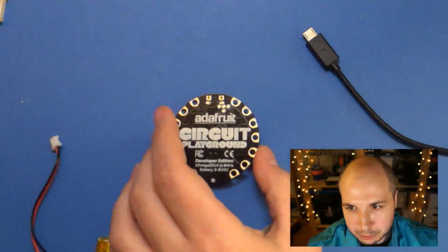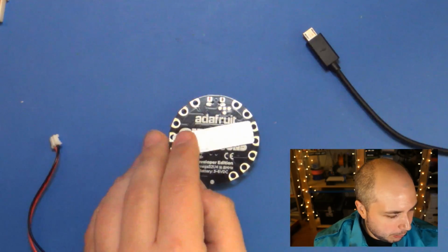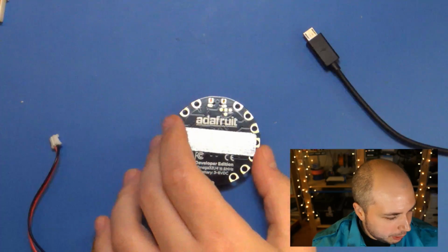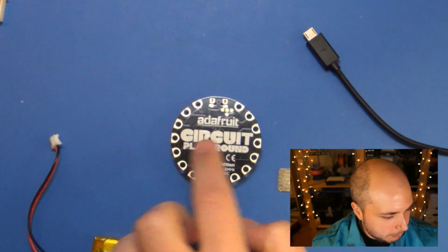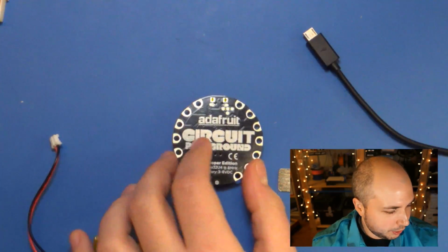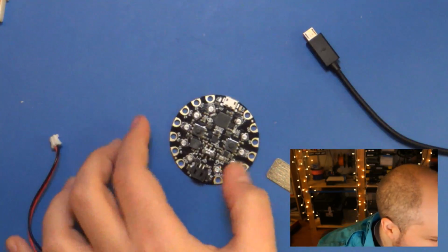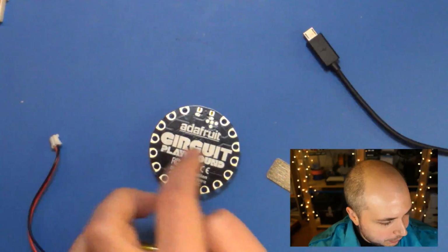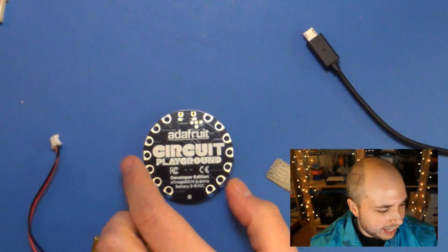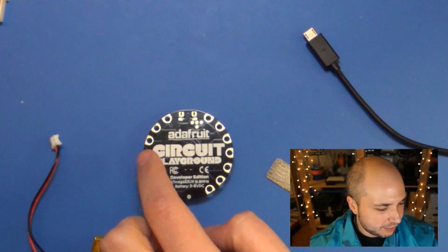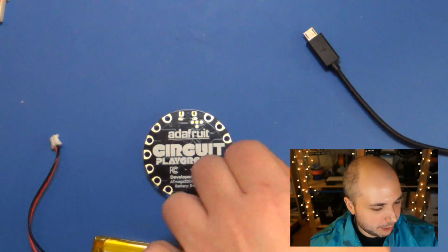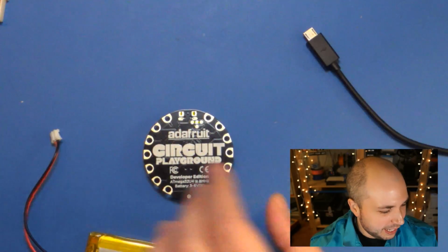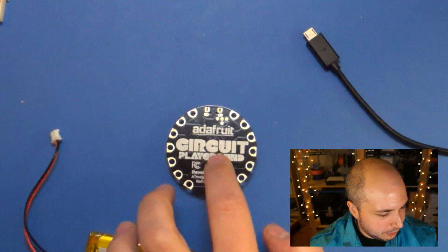So I'm thinking, let's take Circuit Playground and put this metal part on the back there. Then I can attach the magnet like that. But I do want to be very careful, because this is metal and there are pins on here, or these output connectors, that could short out. In particular, this one on the left right here is 3.3 volts. This is ground right here. If I short both of these out, that would be bad, because that 3.3 volts is the output of the regulator. That's going to go straight to ground through this piece of metal that has almost no resistance at all. That could just completely kill your regulator pretty easily. So I don't want this metal to touch Circuit Playground.